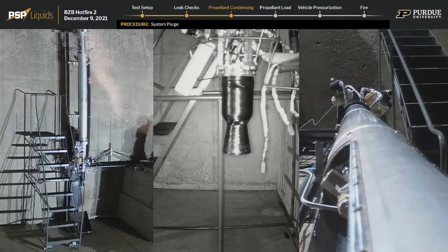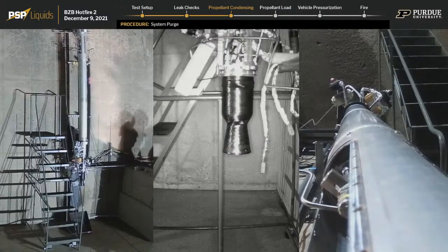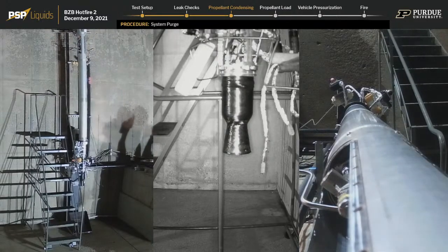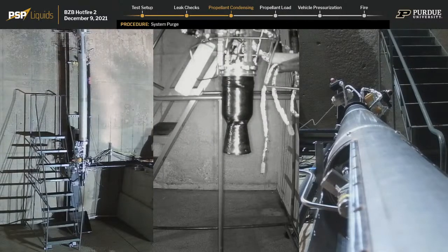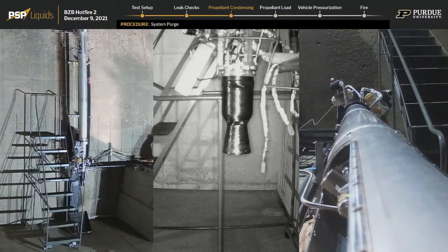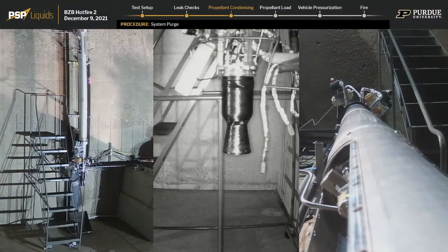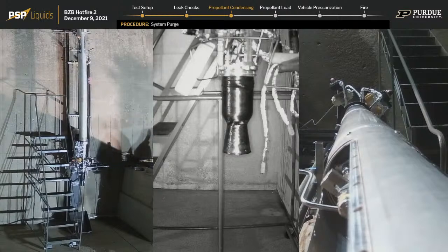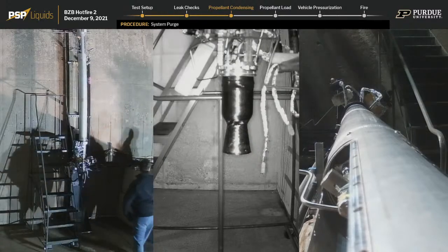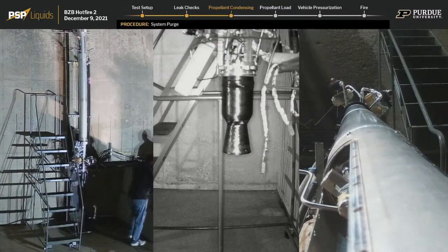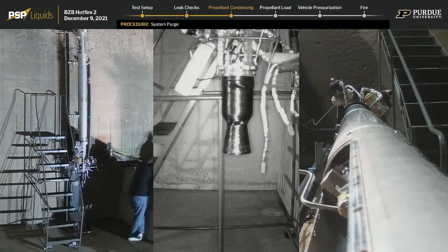So, circling back around to the igniter installation, what's really going on there? So, yes, as we stated before, the igniter is simply a chunk of solid propellant on a stick, essentially, with an E-match connected to it. We found that this is the easiest and simplest way of starting up our rocket and igniting the flow. And it has worked for us in the past very well. We found really no reason to complicate a system when we can just do it the easy way.